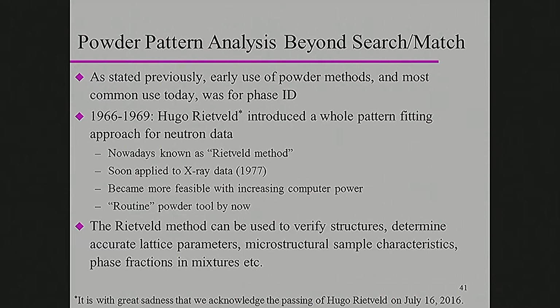Now, beyond search match, the big step forward was the Rietveld method. Okay? It was in the late 1960s that Hugo Rietveld introduced a whole pattern fitting approach, and that really put powder diffraction into a different time. Okay? Instead of simple search match, you could all of a sudden do things. He did this originally with neutron data. In 1977, R. Young actually applied it to X-ray data, and the increase in computing power is what has made it a routine tool nowadays.